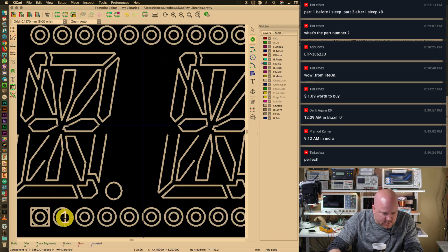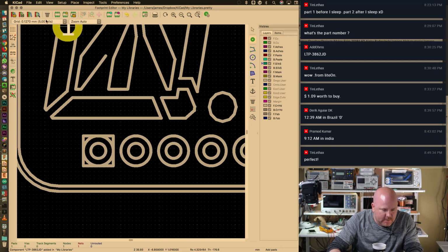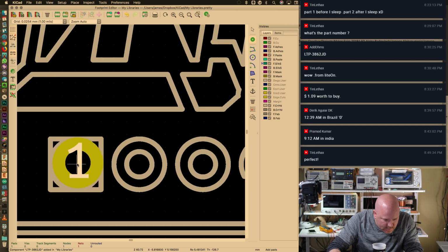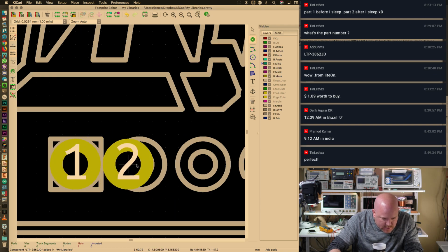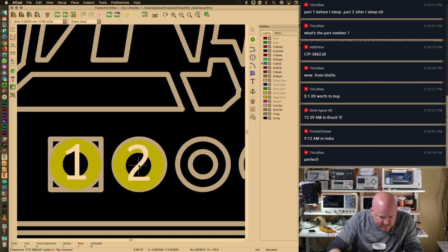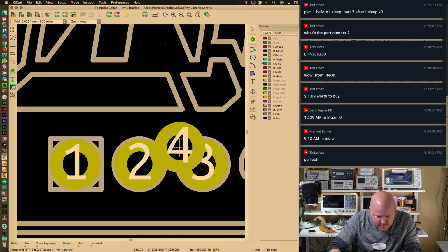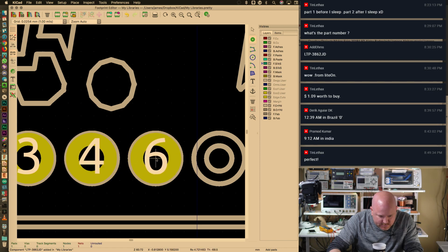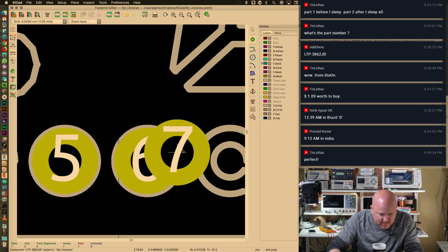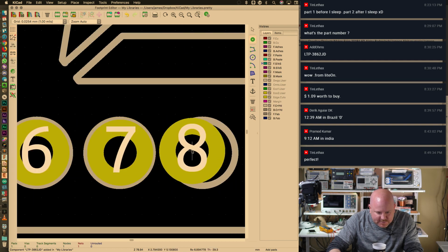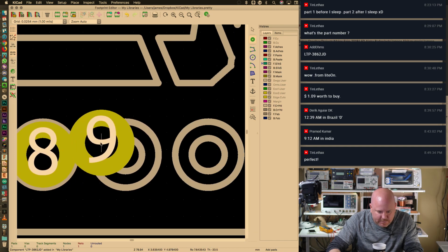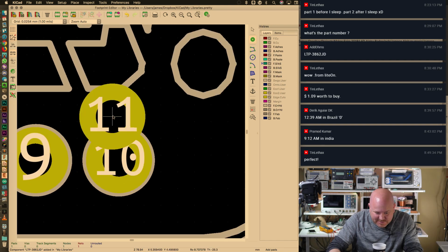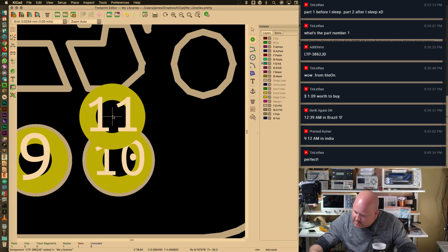So now the idea, I'm going to do this. Let's go to a slightly finer grid of like a mil. I'm going to come back and use the align tools in KiCad as well, but I've never tried that on a pin, or on a hole definition, so I'm just going to wait until I get all of these in place. I mean, the reality is I made the holes slightly larger than the pins and their tolerance, so they can all be off a little bit. It'll actually make soldering a little bit easier if they're slightly off. So 10 and then 11.